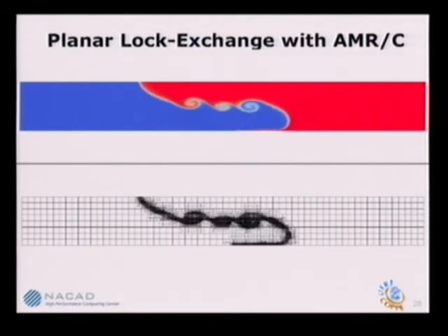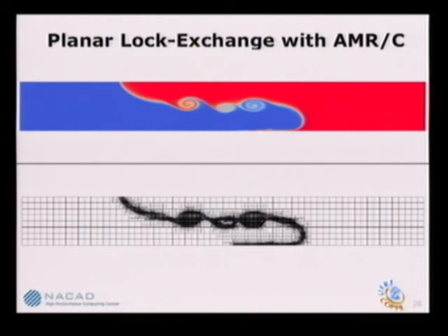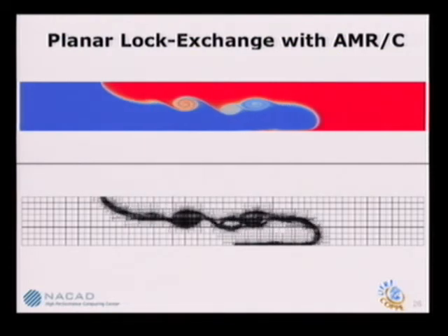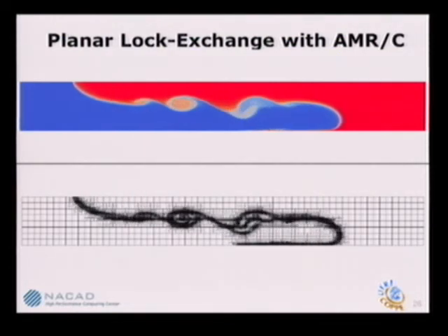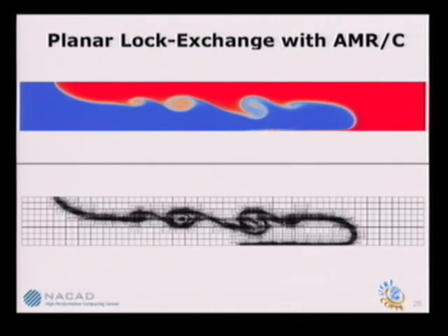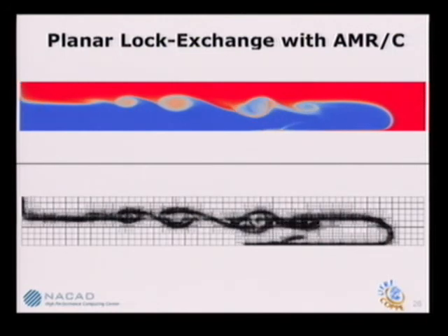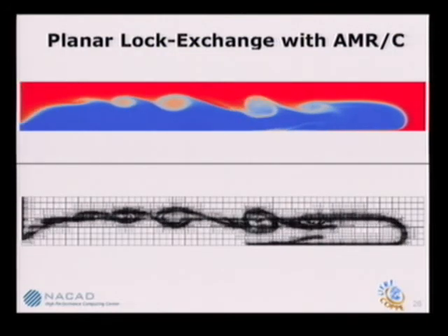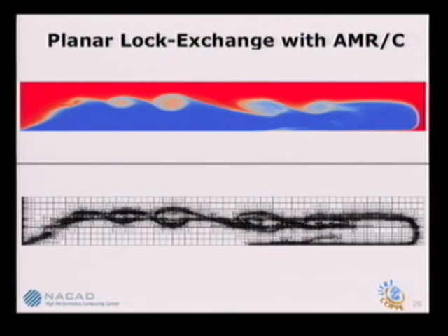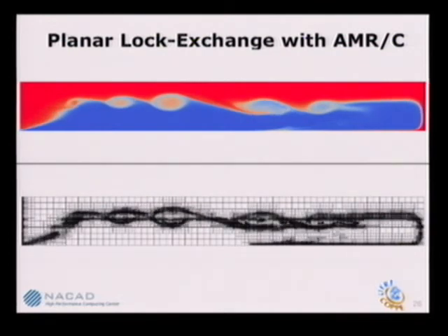You see the formation of the Kelvin-Helmholtz billows, the nose of the front. And we have resolution where we need to have. Again, we should have stopped the computation before, but anyway. Adaptive mesh refinement can follow all the features of it, right or wrong, but we should have stopped the simulation before.